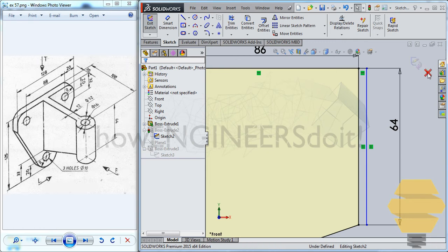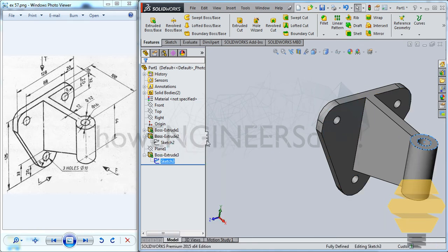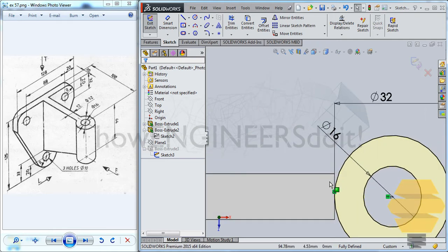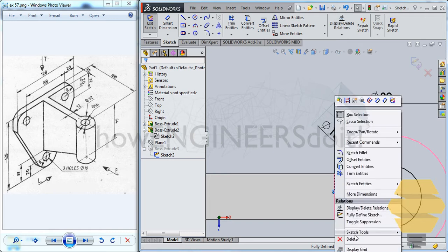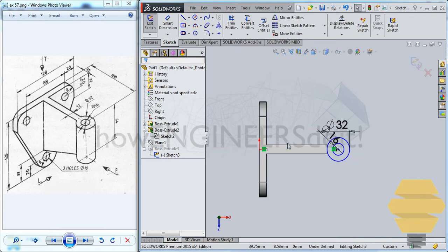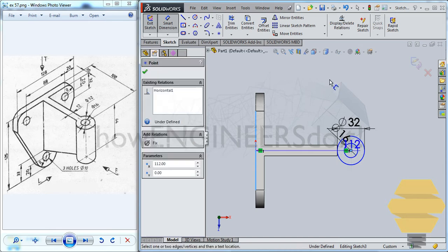The reason being that this structure here, you can see, Ctrl 8, this has a tangency here as well, so even that will change. So you can just delete all the dependencies, delete this tangent, and instead of doing that, you know that from this face to this center it's 100, so you can simply give from here to here 100.